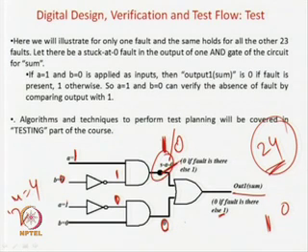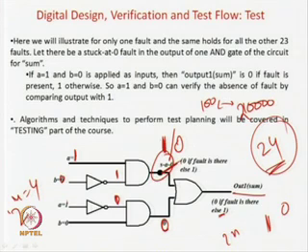If the number of nets in a circuit is n, then how many faults can be possible? 2n. In a practical circuit, if there are 100 inputs, you can think that there are around 10,000 lines in this circuit. That is an approximate number. So how many faults are there? Stuck at 0 and stuck at 1, so 2 times 10,000, 20,000 faults are there.